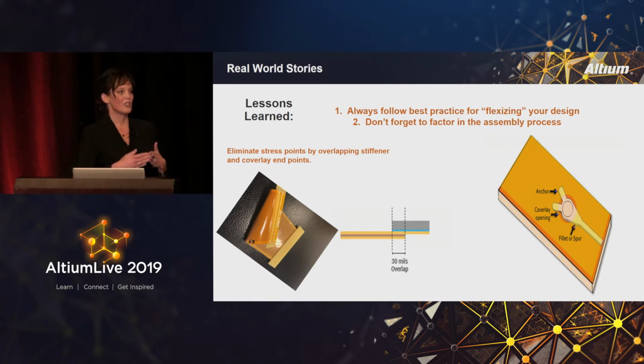It's probably one of the highest stress areas in a flex design. So we always recommend teardrops. This one wasn't. Nobody really knows why. So they added all the fillets, ran the boards, and everything worked great.